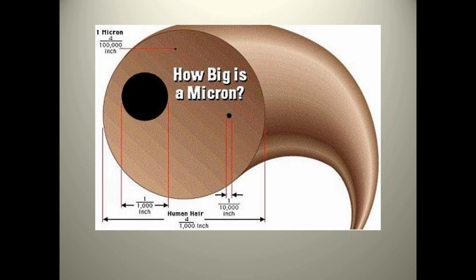Well, Baldwin makes filters in England, but the Baldwin filters are just paper cellulose filters. They'll never filter particles down to these real low micron levels. So you have to be careful with these. But the Baldwin filters are a fourth or a fifth of the price of the good low micron filters. So you get corporate procurement people and people that don't understand the beta ratings. They actually buy these cheap filters, and they actually start getting equipment failures when they do that.